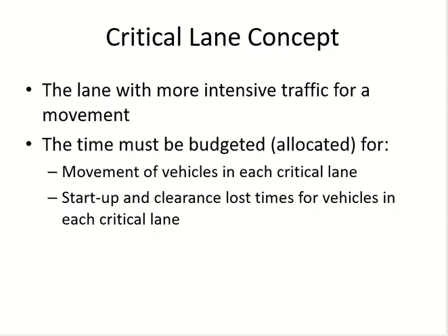Cycle length, right? Cycle length is what? Time. So the critical lane should also be the one which needs more time. And now you know that more time does not always mean more volume. Yes. So turning can slow you down. What else can slow you down? If you are taking a turn versus going straight, turning will take more time, it will be slower, and it has more radius, right? Straight is less distance, turning is more distance, right?